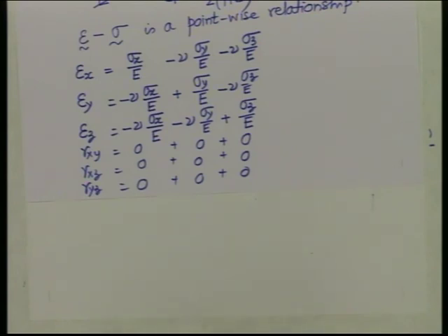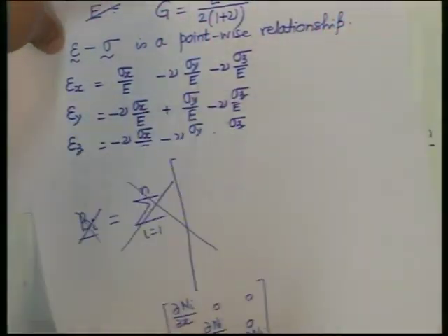So, we have applied all the 3 normal stresses at a point, but then you do not have only 3 stresses, you have more than 3 stresses at a point. What are the other stresses? Shear stresses. Shear stress is always applied in pair, always at a right angle.